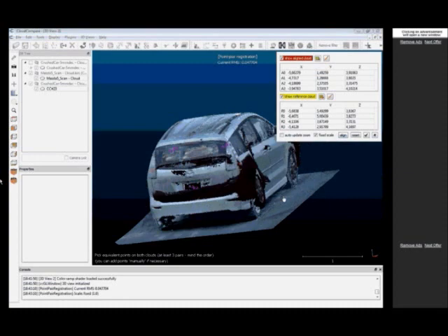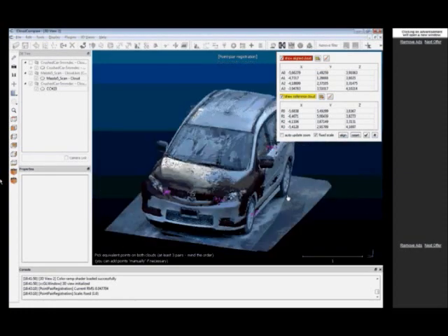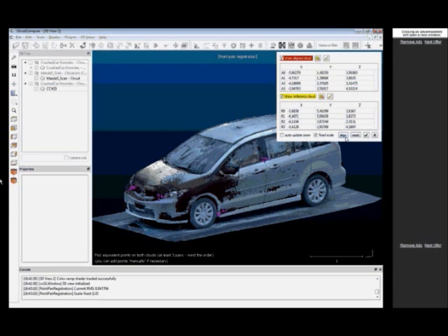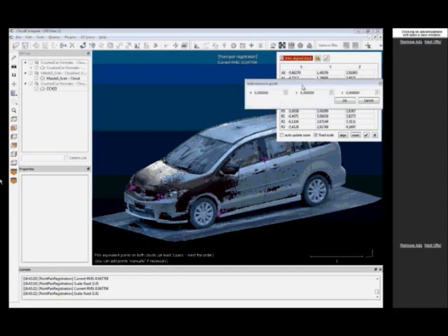It may have gone too fast. Well, you see the RMS error, root mean square, which is quite good for two cars that are quite different, below 5 centimeters here. And of course, you can repeat the process. You can add pairs of points if you want to get a more accurate or more robust result. You can also input manual points, which is quite useful if you have a total station, for instance.